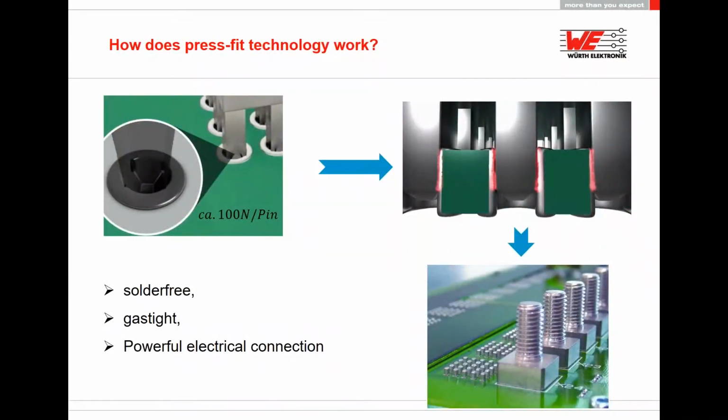So the main question we get very often from the customers: what is press fit technology in general, and how does this technology work? So what happens when we press the pins into the PCB? The technology is quite easy. It's a solder-free technology, so we don't have any solder process, and we also don't have any thermal processes.